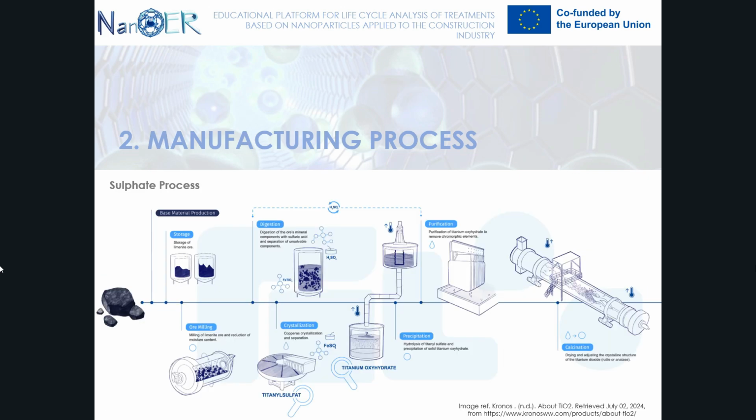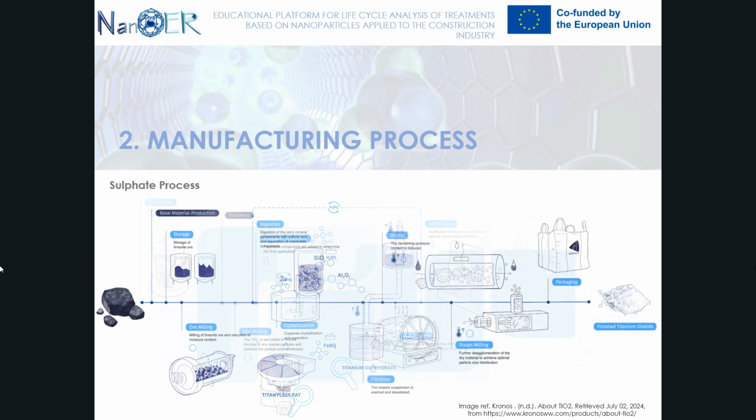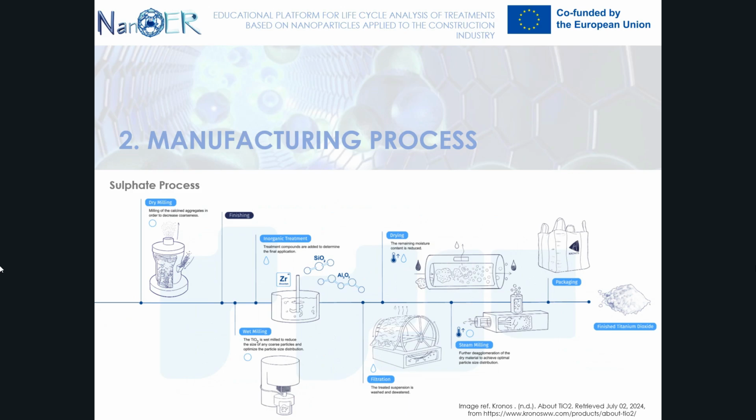Each stage of the sulfate process uses some form of sedimentation or filtration to remove impurities. The crystallizer stage is important for bulk removal of iron sulfate. If not sufficiently removed, FeSO4 will cause an undesirable yellowish tinge to the final TiO2 product. The FeSO4 byproduct is often sold into diverse industries such as water treatment chemicals, cement additives, and even food-related additives.